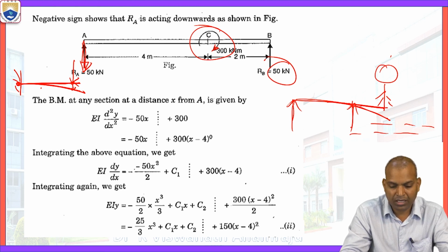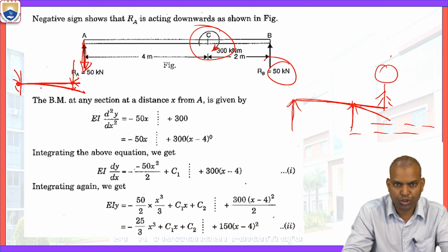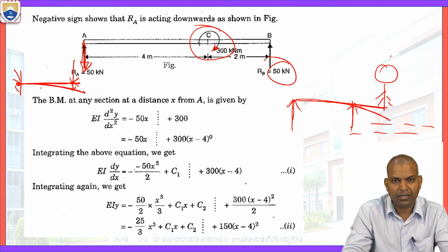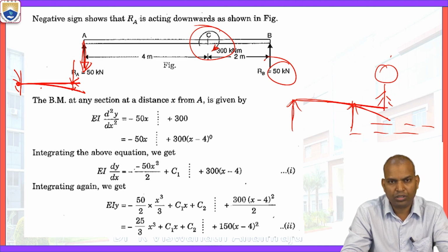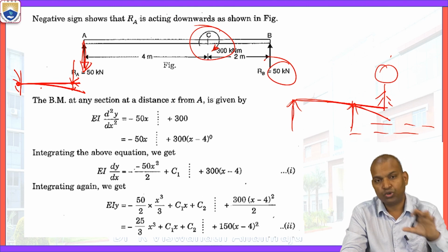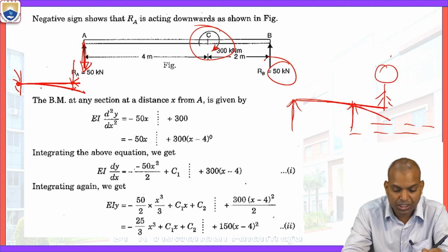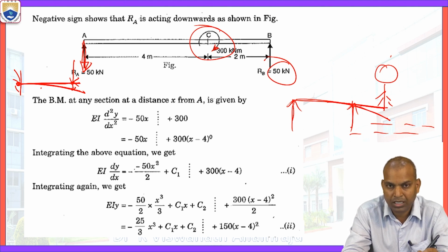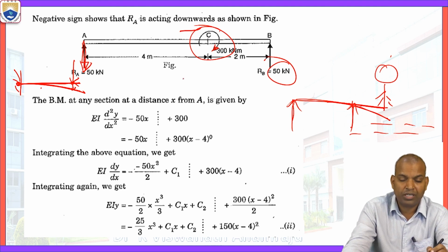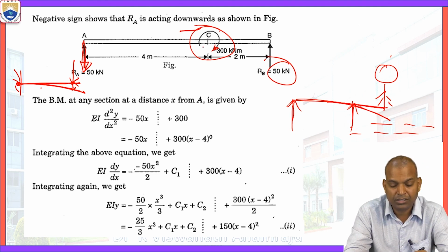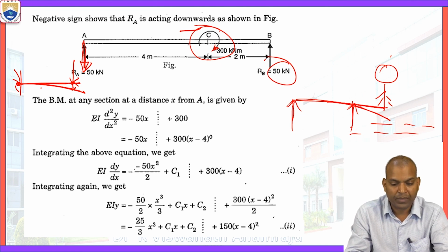Now, in this session and the before session also, we considered three unique models for an overhanging beam and simply supported beam, when the beam is acted on by a concentrated load, a uniformly distributed load, and also a combination of uniformly distributed load and concentrated load. And one more, in this session we considered there is no concentrated load, no UDL, and no uniformly varying loads. We considered only moment. The moment acted here in the clockwise direction with the value of 300 kilonewton meter.